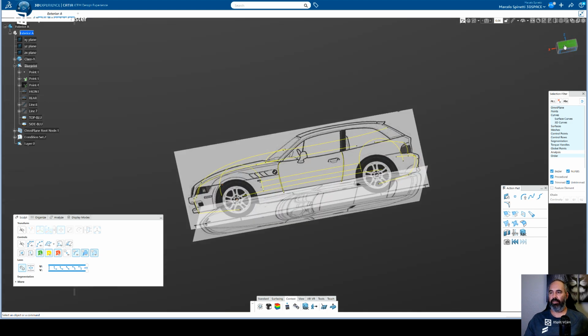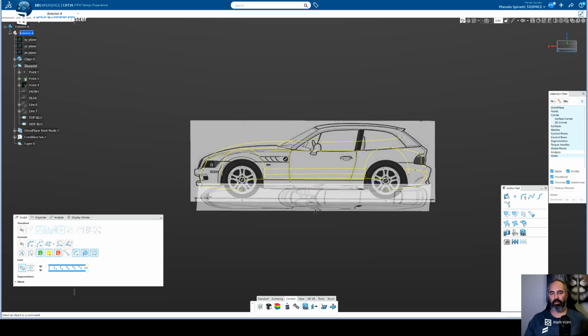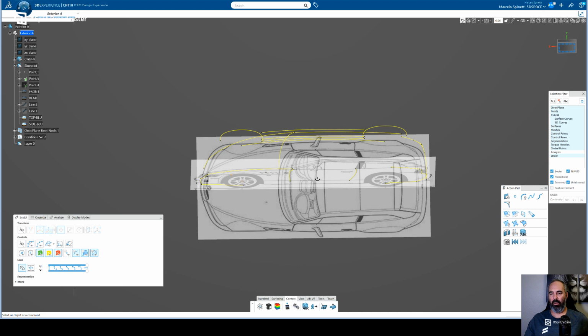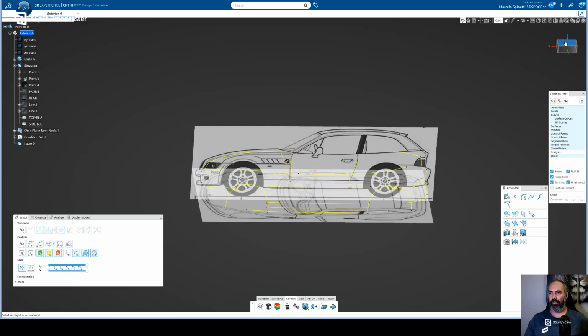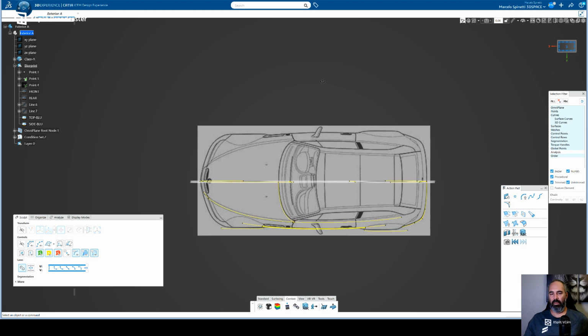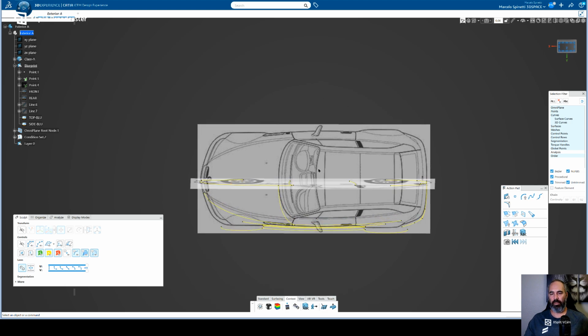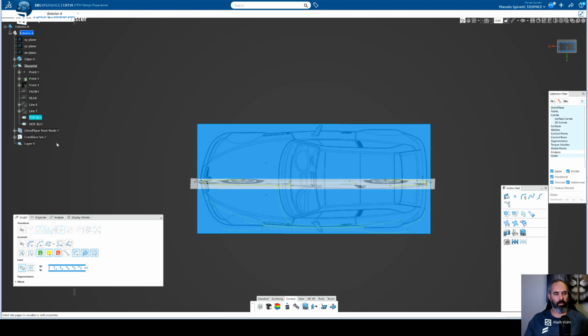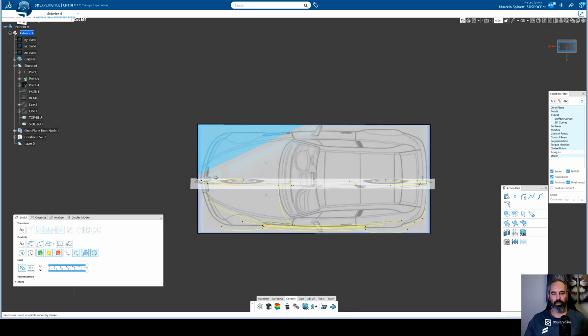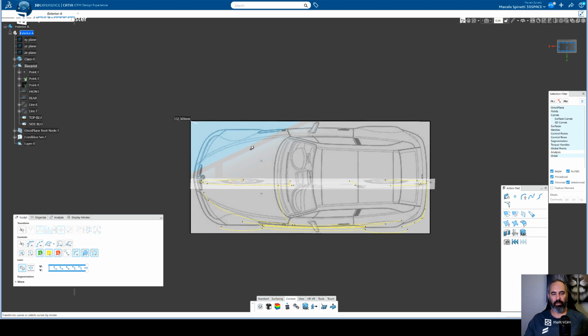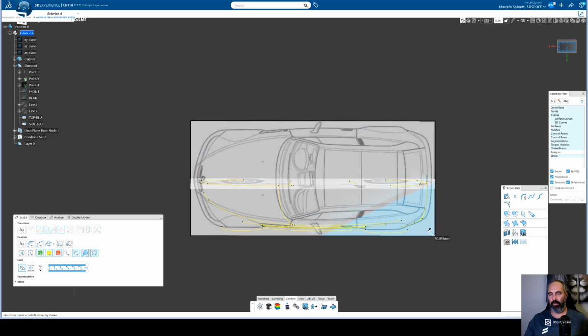And there are two ways to change the size of the car. So let's go to top view and change this one. Oh, pickable. No, it's not pickable. Properties, pickable. And twice. Let's increase to here, and increase to here.